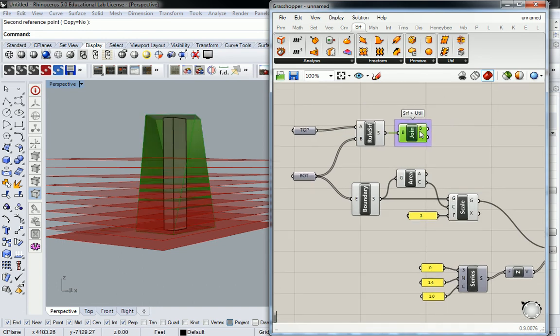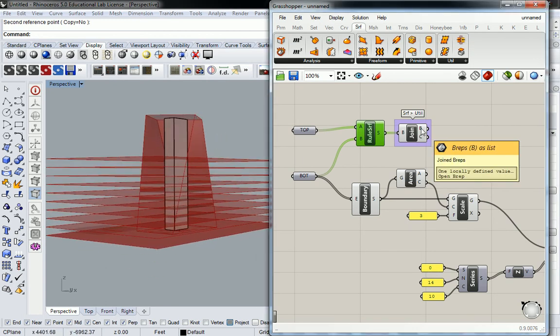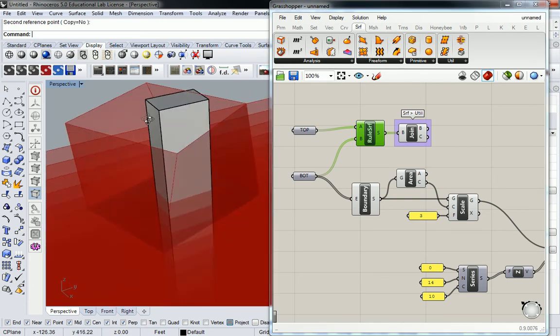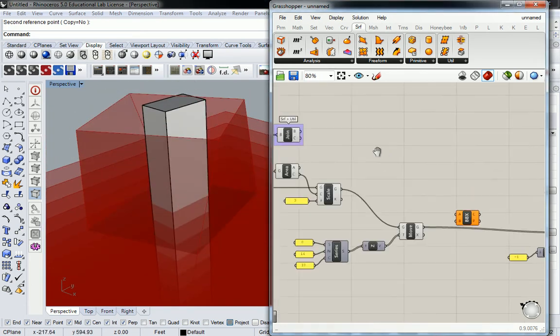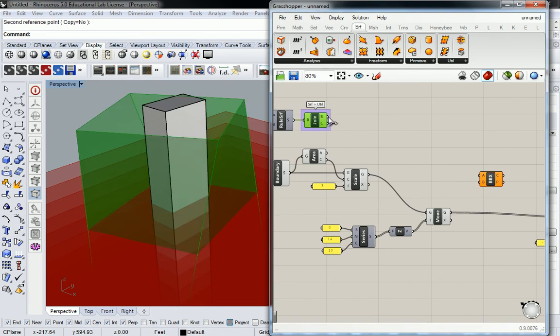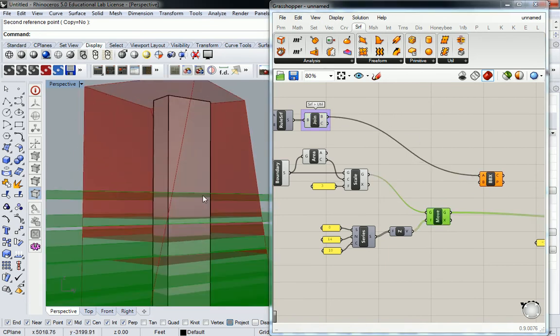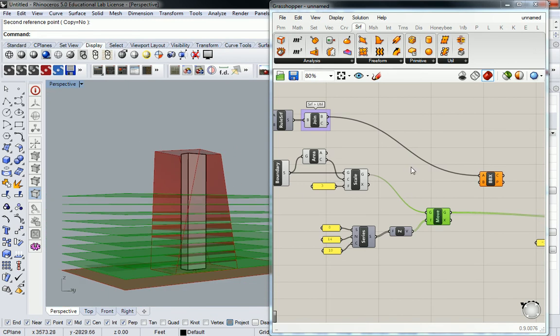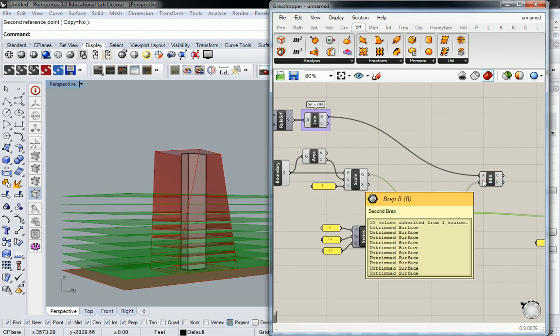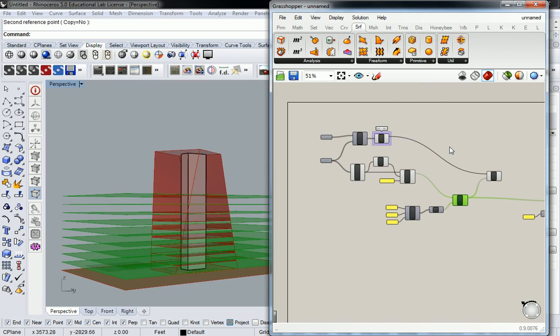Okay, so that creates one solid surface. I'm going to get rid of that here for a sec. So now that's one open Brep. At the top, it is not complete, so it's just a representation of my outer boundary. And I'm going to plug this into A, and I'm going to take my array of floor plate datum levels. Yeah, I think I'll call them that. And I'll plug that in here. Okay. Make sure you hide everything except for that.